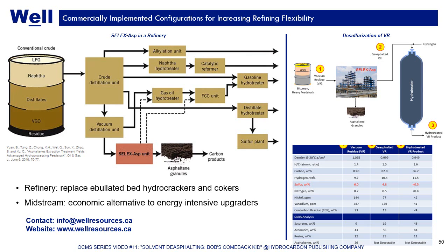Desulfurization of this DAO allows for the production of fuel oils that meet the low sulfur content specifications mandated by the upcoming IMO 2020 regulation. In one instance, a SELEX operator reconfigured its operations to process FCC slurry oil for the production of needle coke, a high-value, high-purity carbon product used primarily for electrodes in the metallurgical industry. These examples showcase the processing flexibility that SELEX offers.